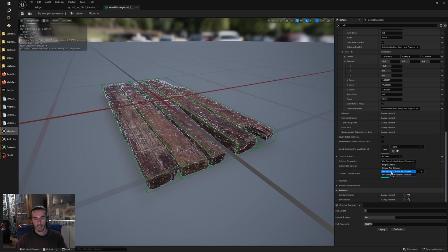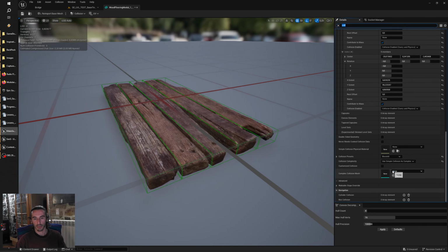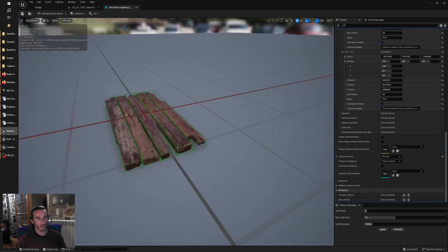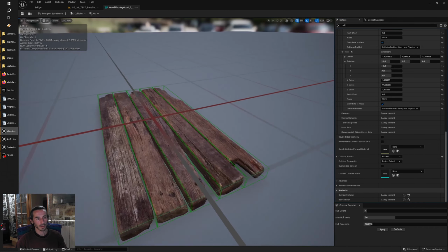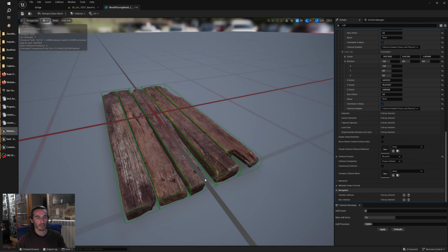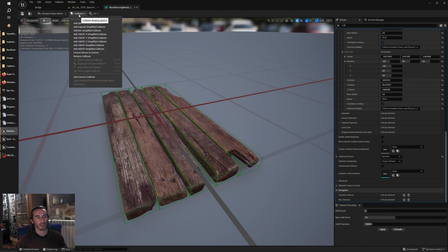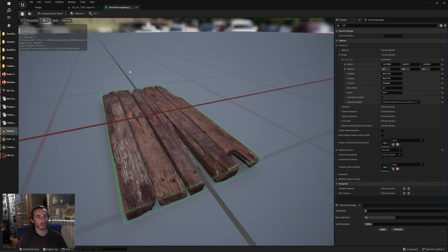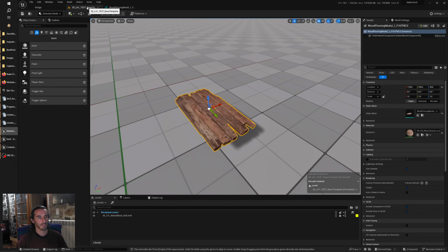So just change this to project default or use simple collision. And here it's a choice. You can consider it's fine to have 5 boxes, or you can prefer to make one simple collision mesh for the wall module. And you just have to remove the collision and create a new one, and this box will surround your model very finely.